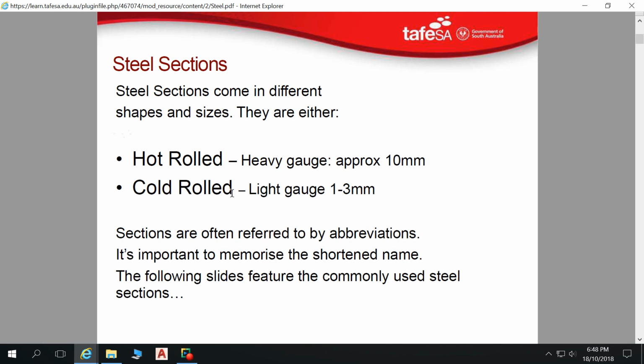So that's any steel that's a thinner gauge that comes from a roll of coil steel that's rolled out and cut and bent into various different shapes. So a lot of your Stratco sheds and things like that, all their framing members are cold rolled steel. So it's thinner gauge rolled into a C section or a Z section, whereas your hot rolled, that's all your much heavier steel.